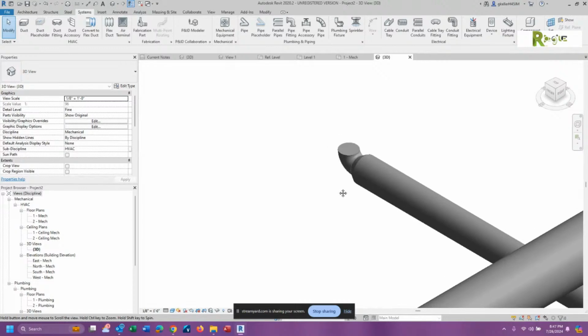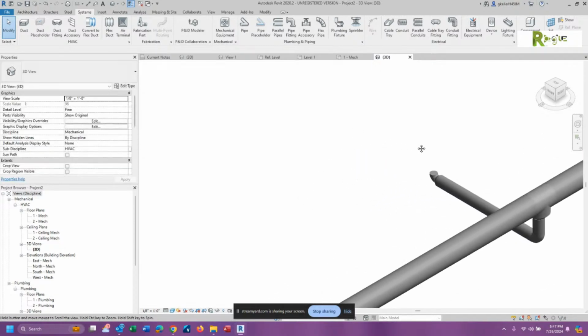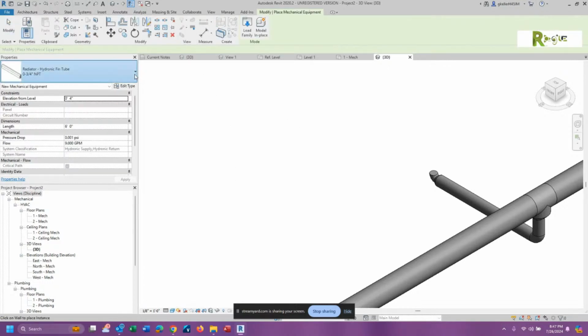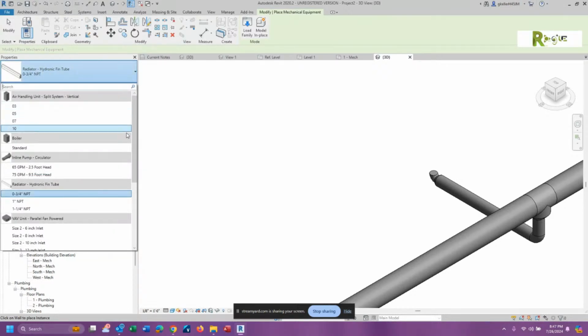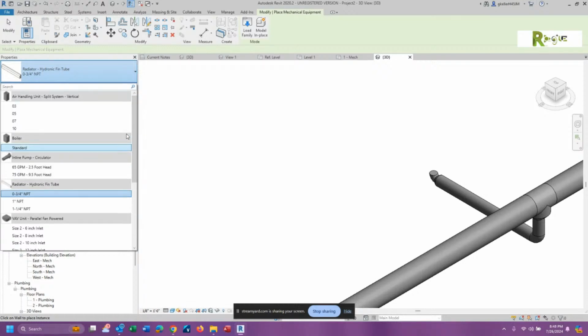That makes sense? Yep. Now, the truth is that Revit was never really intended for you to draw pipe like I'm asking you to draw pipe. What it was intended for you to do is to put some mechanical equipment in there, let's say the mechanical equipment is a hot water heater. It was then looking for you to put in all of your sinks and connect all of your sinks to your hot water heater, and then it would run all of that stuff. And if you don't have the one you're looking for, what you do is you go to load family.